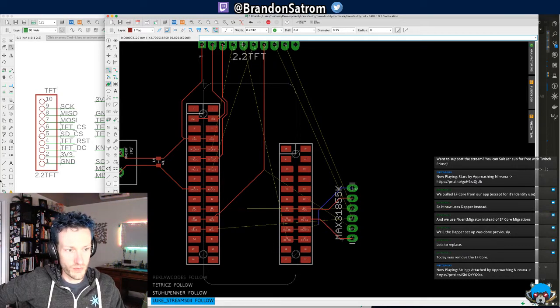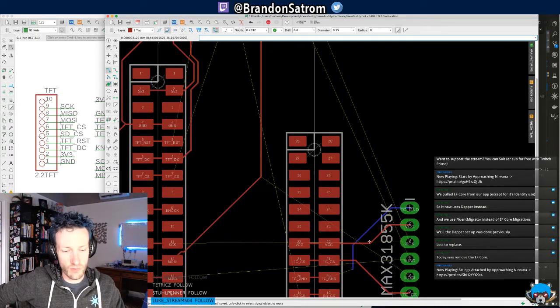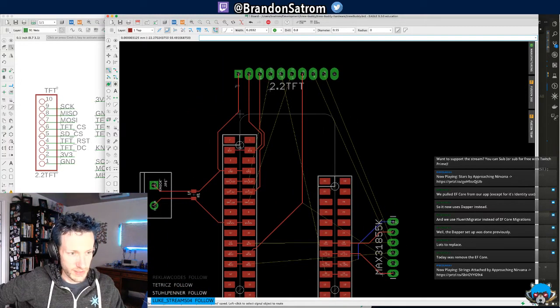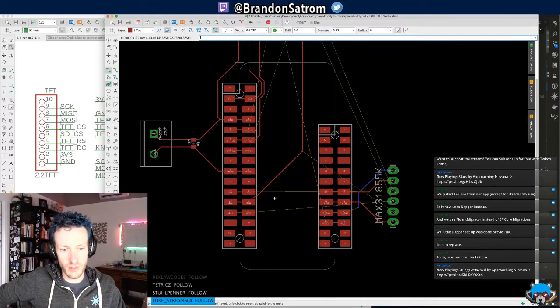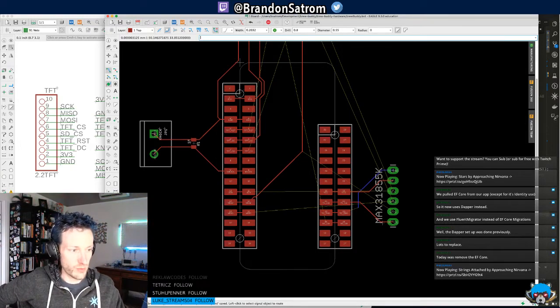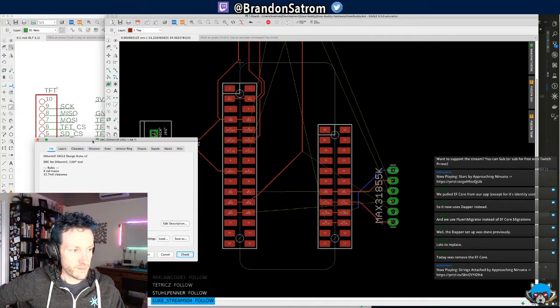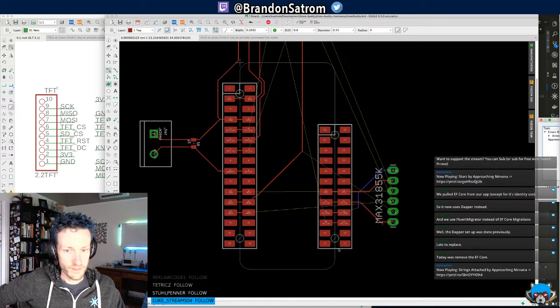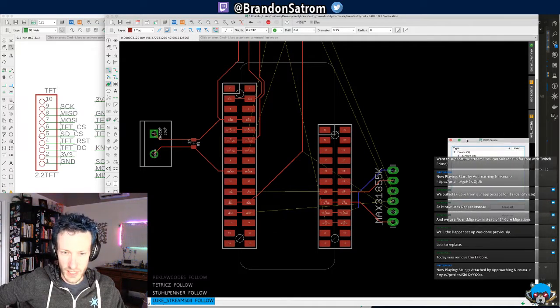My constraints are that I can't have wires of the same color cross. I can't cross certain dimensions, like these white circles here represent holes in the board, so I can't go through those areas. So it ends up becoming a puzzle of what are the shortest lines I can put between the pieces on this board that doesn't violate any rules. And I can run DRC to see what sort of issues I have. Right now I still have 9 air wires, that's expected. I don't have any other potential issues right now.